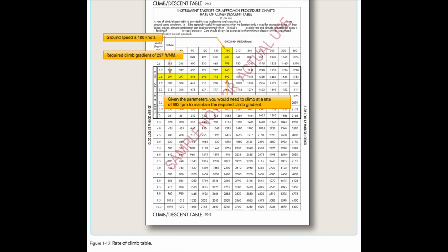Departure design, including climb gradients, does not take into consideration the performance of the aircraft. It only considers obstacle protection for all aircraft. TERPS criteria assume the aircraft is operating with all available engines and systems fully functioning. Development of contingency procedures, required to cover the case of an engine failure (engine out procedures, EOPs) or other emergency in flight that may occur after liftoff, is the responsibility of the operator.